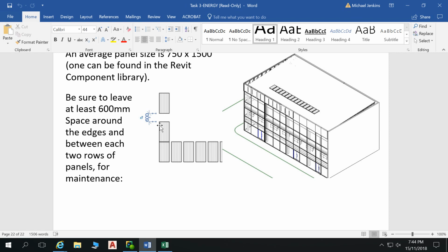You have an L bracket, and you fix that with a roofing screw back down into your purlin. If it's a roof that already has roofing screws, pop that roofing screw out, put your L bracket on, and fix your roofing screw back down. That's for custom orb sheeting. For tiles, it's really annoying because you've got to grind out a piece of the tile, flip it under there, and fix it to your tile batten underneath.